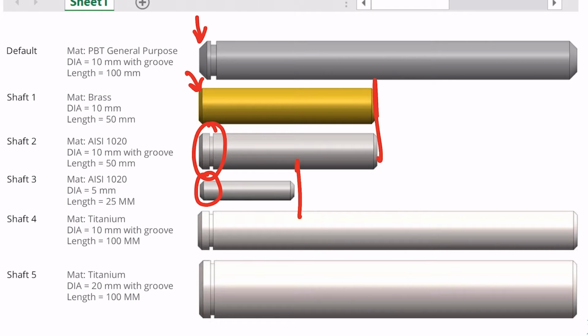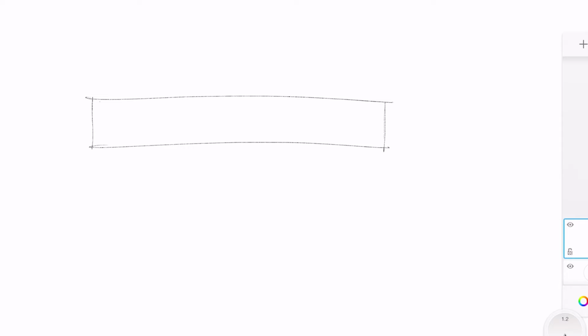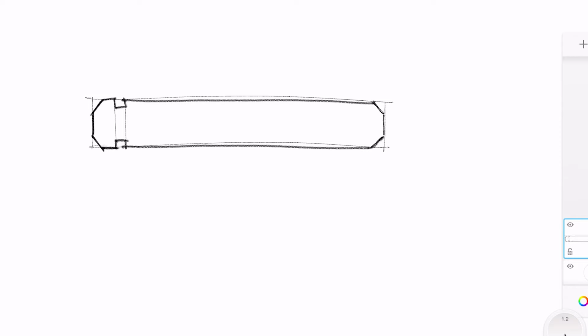And so the first thing we do is we look at these shafts, and we think about them the way that they are in this book. Or if we're designing a product, we envision the different configurations of the product that we might want. And we create what's called a parametric model. To create a parametric model, we draw a sketch. And in that sketch, we want to pull out the key characteristics of the product, the characteristics that we hope to scale or change or manipulate over the full set of configurations that we're going to have.